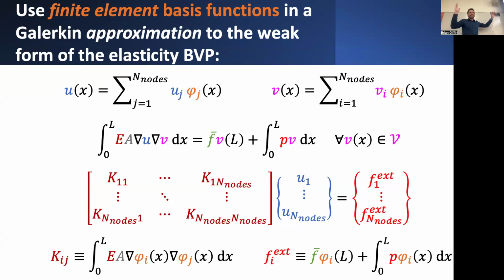Instead, we went through all these extra machinations of converting a given statement of equilibrium of a structure into an equivalent strong formulation of equilibrium expressed as a pointwise statement in a differential equation. We manipulated that further into the weak form, this integral expression, and then we introduced this approximate representation of the solution fields in order to come up with this final result. But it's nonetheless equivalent. So we went through some additional hoops to get here.